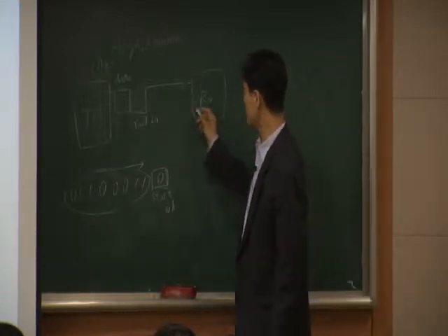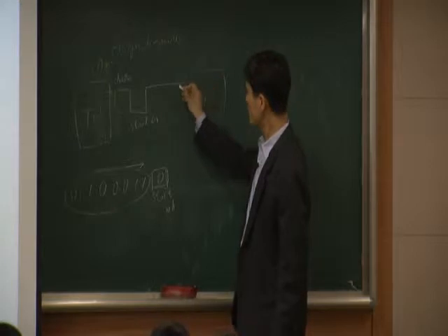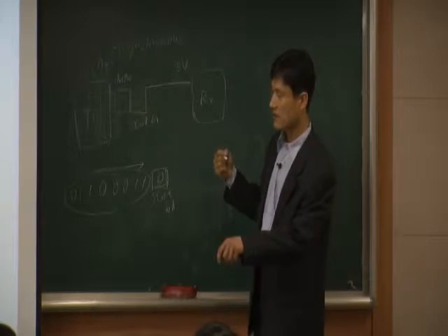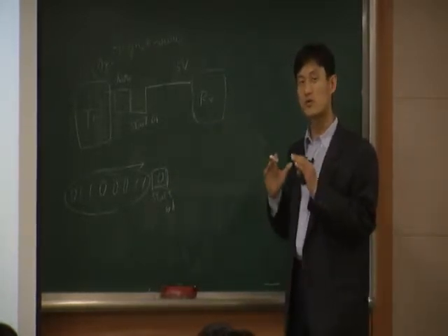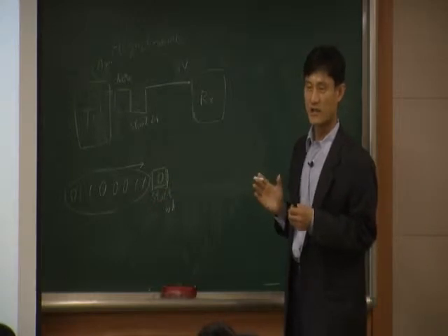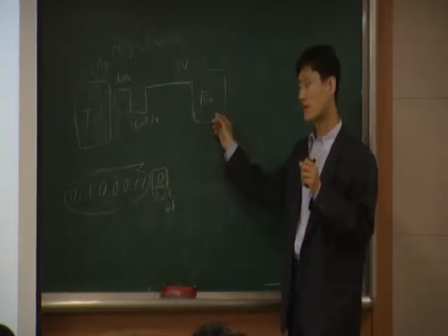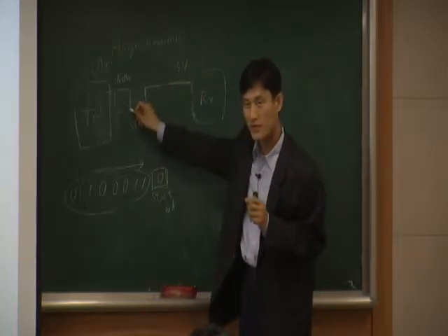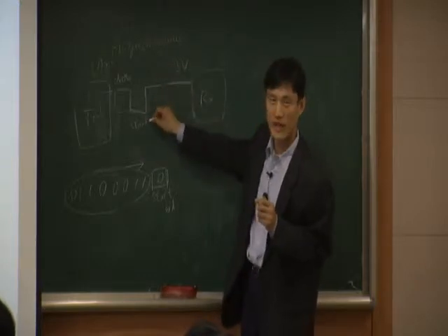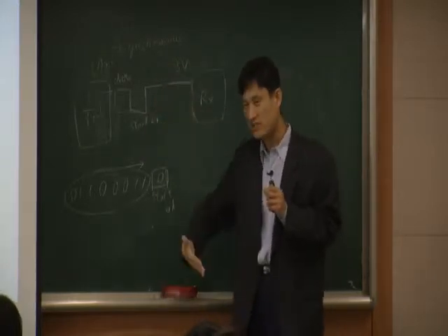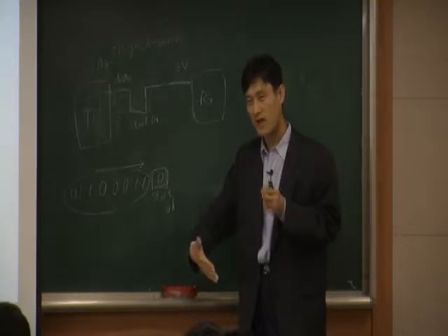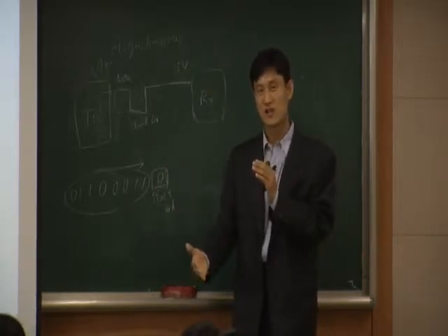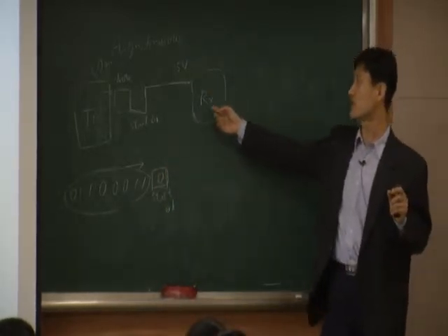What is the receiver looking for? When the receiver receives 5 volts, generally that means idle state. So the receiver is doing nothing because the receiver knows that 5 volts means idle state. What the receiver is looking for is that suddenly these 5 volts drop to 0. It's like an edge, a high to low edge, right? Suddenly the edge starts. That means now data is coming. My data is coming because I have an edge. So this is like edge detection. The receiver is detecting the edge.